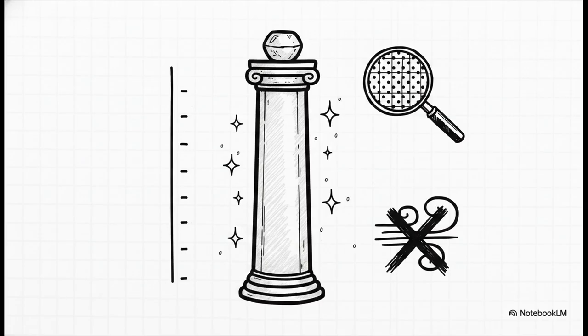That requires 4 massive assumptions. The column must be perfectly straight before any weight is applied. It must be made of perfectly consistent, homogeneous material. The load must be perfectly dead center on the centroid, and absolutely zero horizontal wind or lateral loads can push against the side.